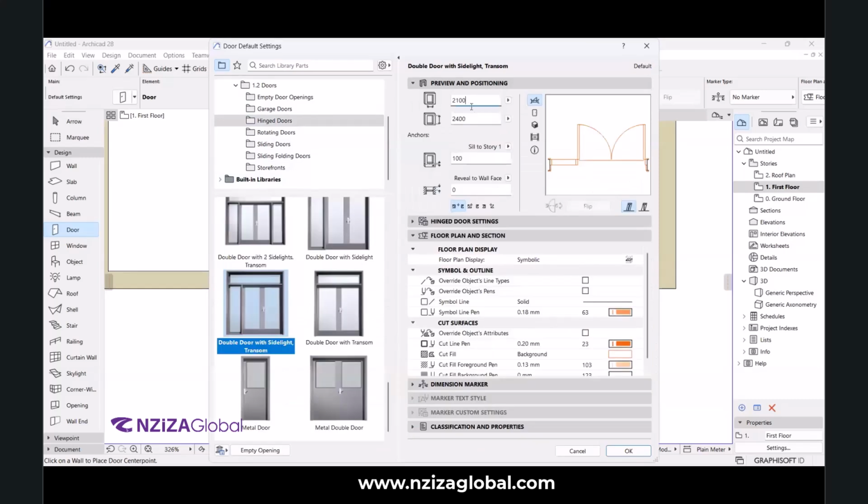Now I'll come into setting. Here we confirm that I will give it 2.8 meter. Here we'll give it 2.5 meter, which means 2.1 of door shutter and 0.4 of roof. Remember here to put 0 to make sure your door is not in the sky. Please do that. You reach me fast, so I don't leave you behind.